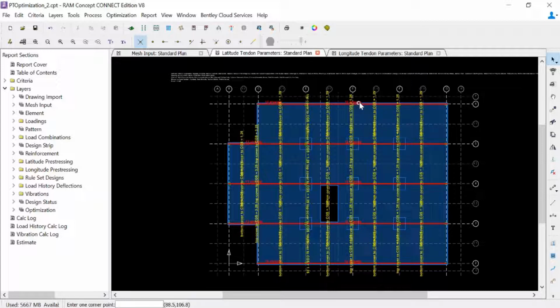The optimizer is still going to be able to break the tendon polylines here, and when it does, it's going to identify this side of the break point and group these two tendons together, and on this side, group these two tendons together. So even though they were assigned the same group, it doesn't necessarily mean that it's going to be a constant number of strands across that break point. The program will still understand that those are part of different regions, and different regions are optimized separately.